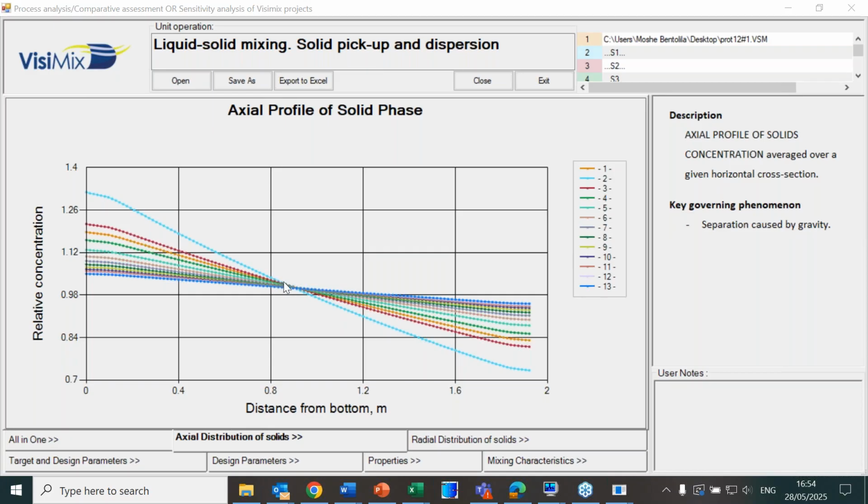We have another question here, a small one. So basically, my lab scale equipment should mimic plant scale equipment? No, it should mimic the plant mixing characterization. Not the same geometry, but the same flow, the same mixing parameters, the same interaction between the materials, yes, as far as possible, or the same critical mixing parameters that are controlling the process, yes, but of course not the same equipment. Normally we are not doing copy-paste of the equipment. This is not the situation.